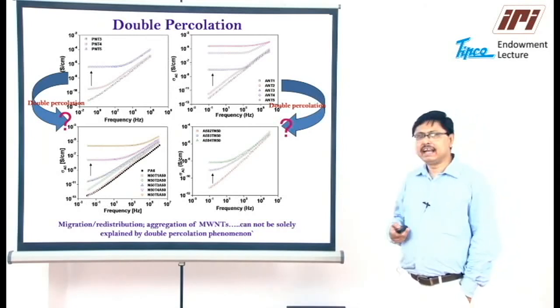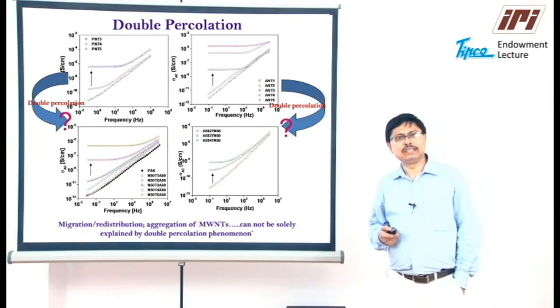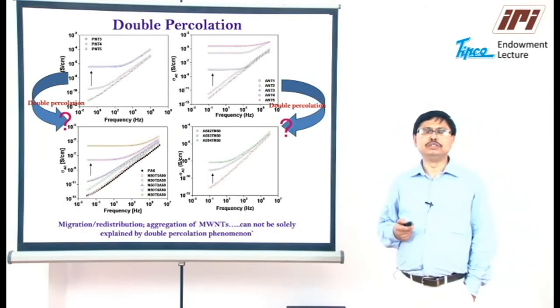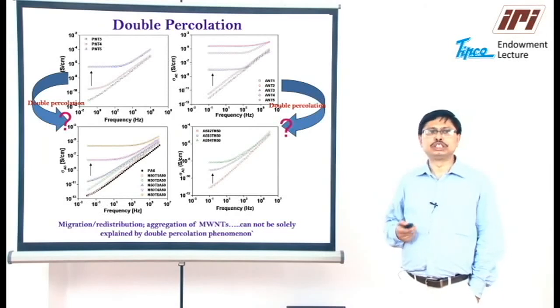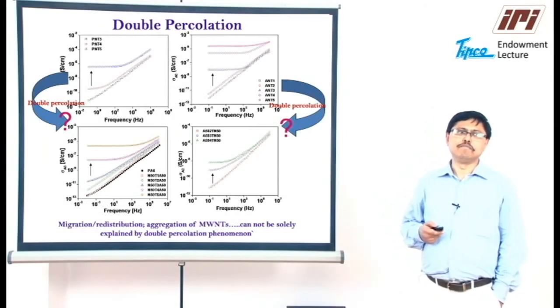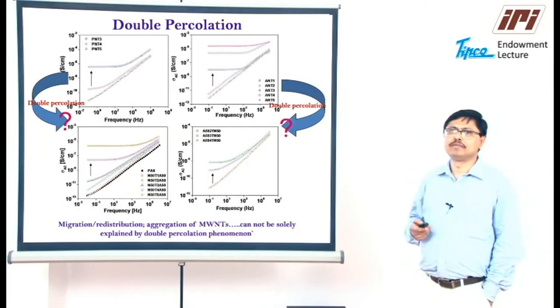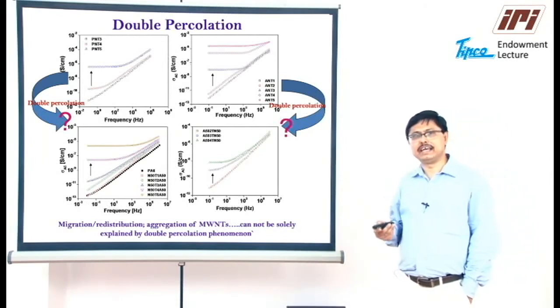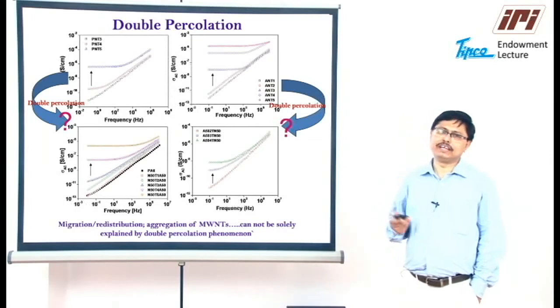Now, one can carry out this melt mixing inside the twin screw, conical twin screw microcompounder using different protocols: a two-step mixing process where polyamide 6 is mixed with the multi-wall carbon nanotubes for 10 minutes, followed by the addition of the ABS, and or vice versa.